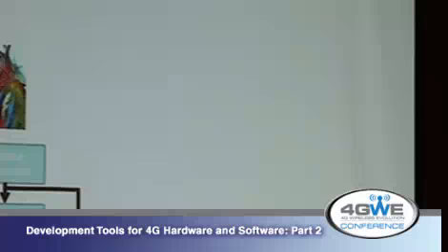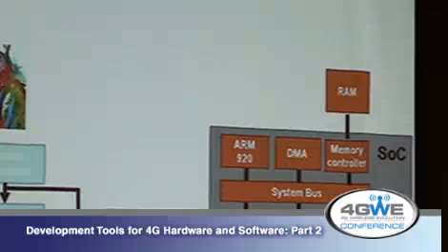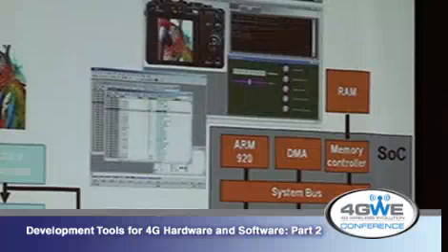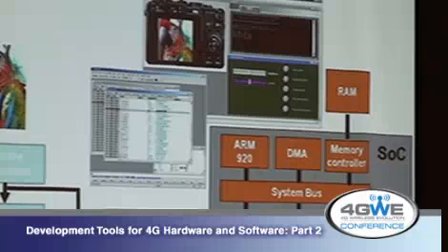And here's an example of how high-level models are used in virtual platforms. I can take, for a picture application, the infrastructure, the picture generation, the rendering, and the analysis, and take this as an environment model and a part of my chip, import that into a virtual platform, and then simulate really in my SoC, which goes into this camera, with the software debugger attached to it long before the actual chip is available.